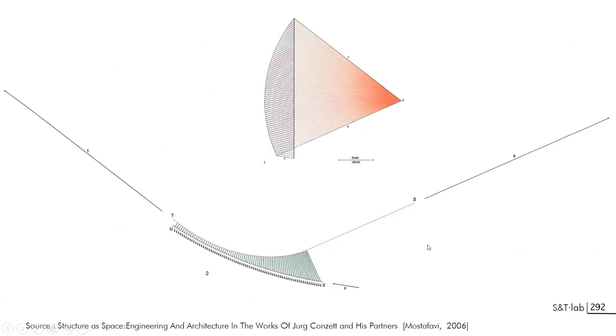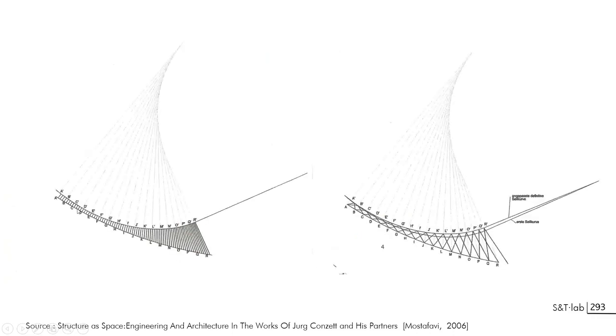And these are the forces in the successive segments of the lower funicular. Working on this, there will be a graphical construction to define the ideal direction of each of the suspended forces. And you would also see that by using skew or diagonal hangers for each of these loads, we put additional tension forces on the several funiculars that will help to stabilize the system and enhance the quality of the equilibrium.